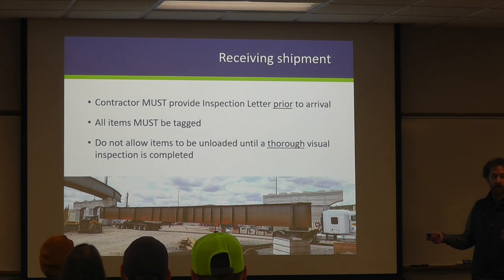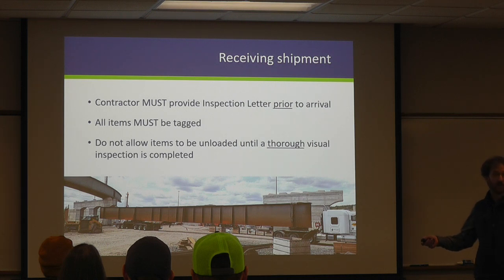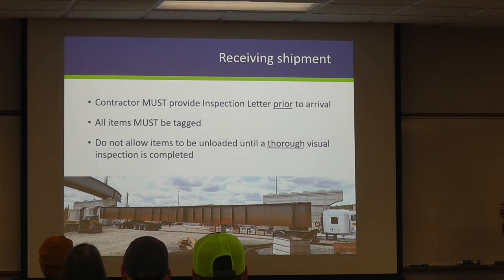To walk along the bottom here, make sure there's not significant damage to coatings that can't be repaired. We've had these come out before where this back end, that whole bottom flange was bent, right? That's going to be a challenge for the contractor to make up their splice in the air anyway. So we want to address those things on the ground. So we want to understand that. And I will tell you that if there's damage that is very challenging to repair in the field, if you let them unload it because they say we'll come back and get it later, they'll never come back and get it later.